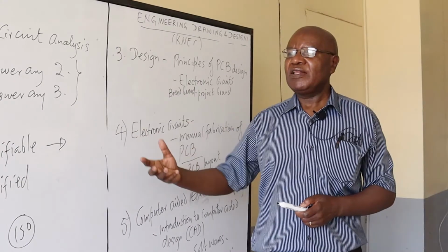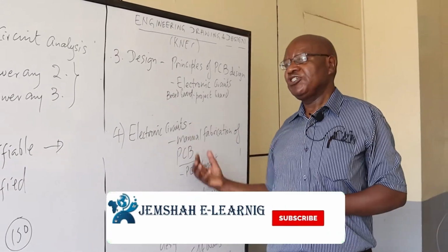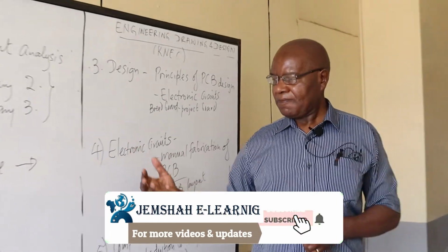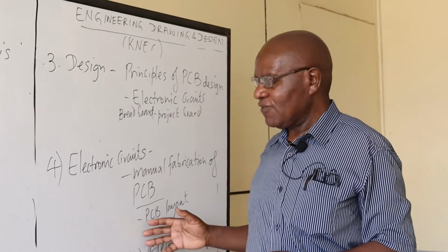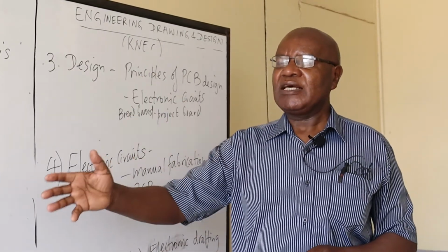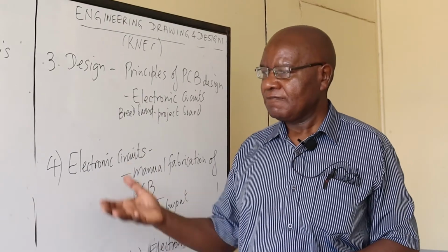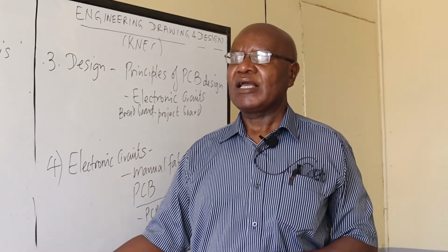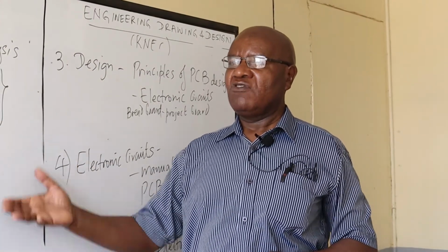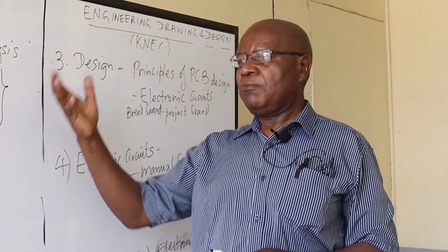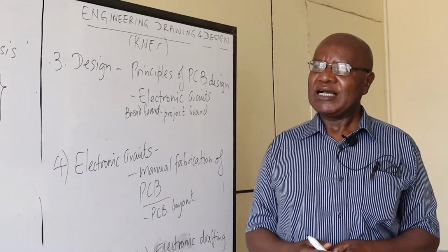In industry, you'll find that they have to make sure that the motor is stopped before you can change direction, an additional control facility. We have also, in the case of the three-phase motors, to test that the three phases are present. Otherwise, in case of one phase failing, the motor should be cut off. And then in the industries, they also detect the voltage levels. If the voltage levels go below a particular point, the motor should be cut off.